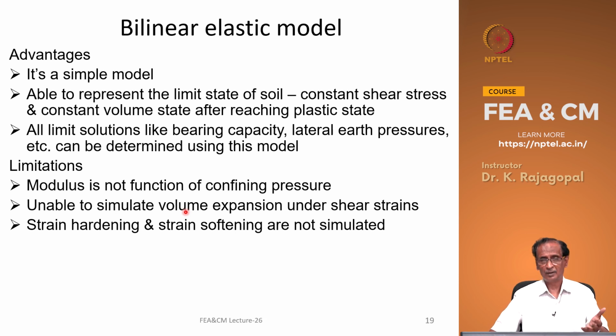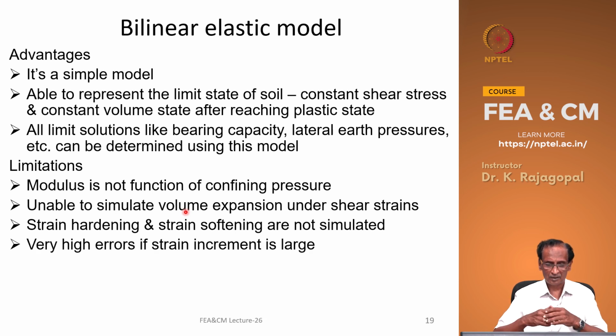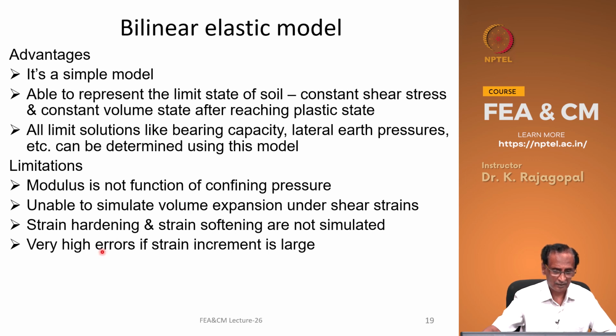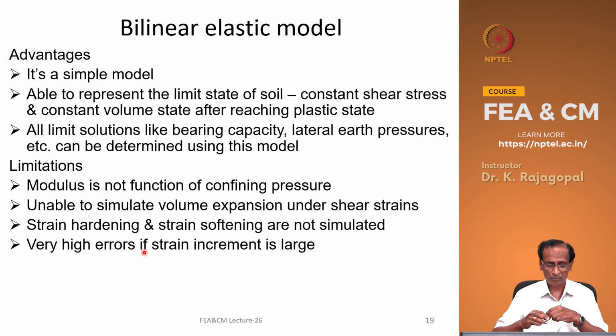We need to go in for better models. And if our strain increment is very large, then we could have very high errors. Say instead of using a strain increment of 0.002, let us say we used 0.1 or 0.005, what would have happened? That we will see through the Excel program, and our errors could be very large depending on the strain increment that we use.